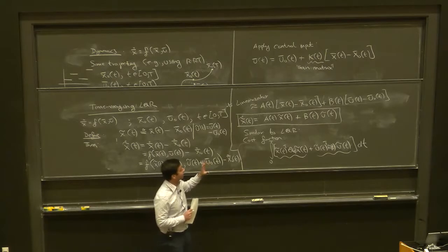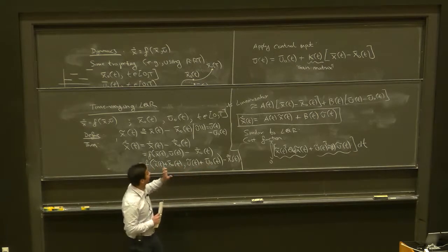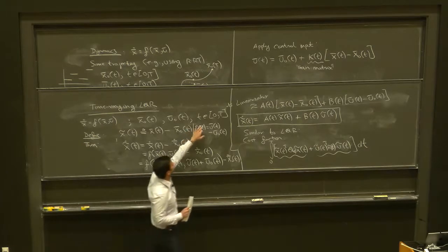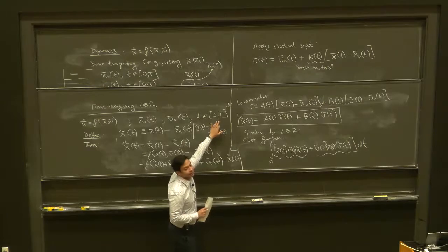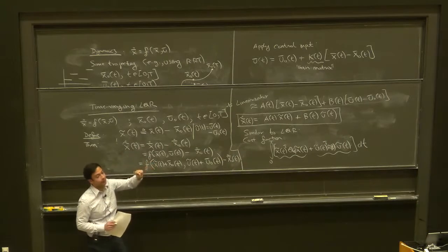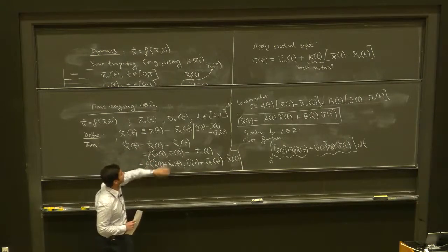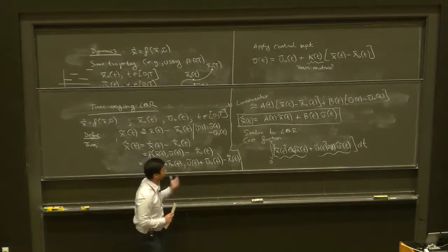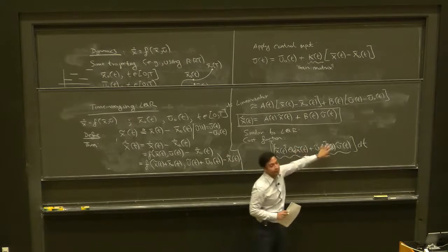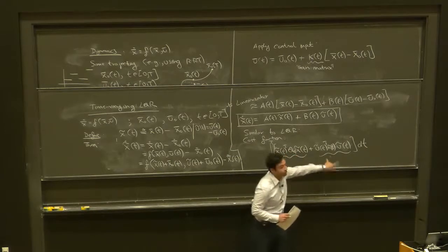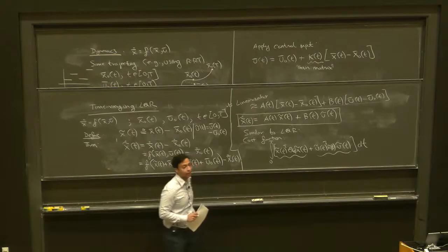We're going to give up on the asymptotic stability part here, partly because it isn't well defined. Our world ends at capital T; we're not even defining the trajectory we want to be at after capital T. So we're not going to ask for asymptotic stability or any other kind of stability. We're just going to say this is our objective, and it has fairly clear intuition: don't deviate too much in state and don't deviate too much in control input. We're just going to try to optimize this.